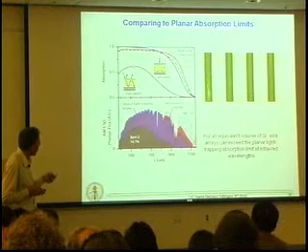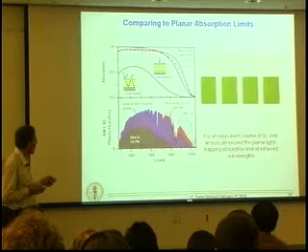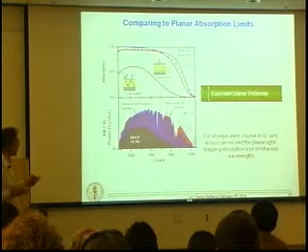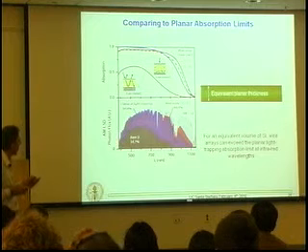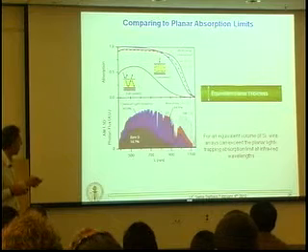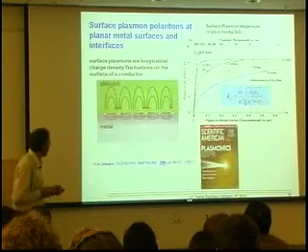And a thing to mention is also that the wire arrays have an equivalent volume of a thin film. So if the wire array is 100 microns thick and it has a volume concentration of 4%, it's equivalent essentially, in silicon volume, to a planar film that's 4 microns thick.